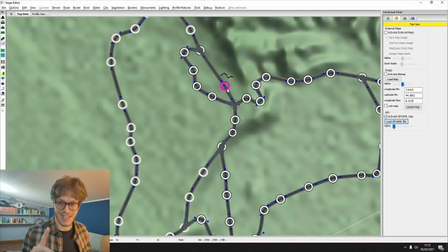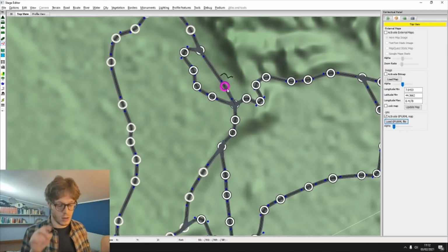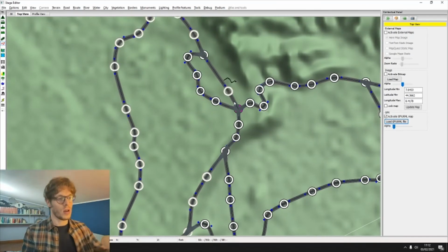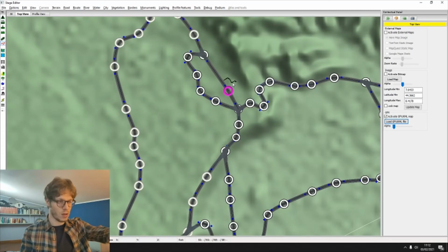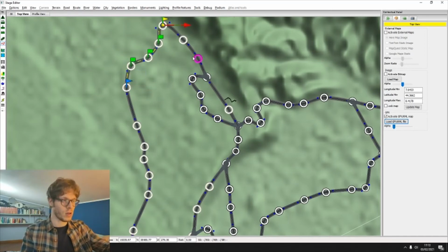Well, another important thing. It's better to start the route 2 kilometers before the real departure and finish the route 2 kilometers after the real arrival, because when I put the departure and arrival line in the route, this works for 2 kilometers after the first point of the spline. So if I wanted to start my stage here in the center of Bra, it's better to put the real departure here, because I have to consider at least 2 kilometers from the departure. If more, better, but at least 2 kilometers.